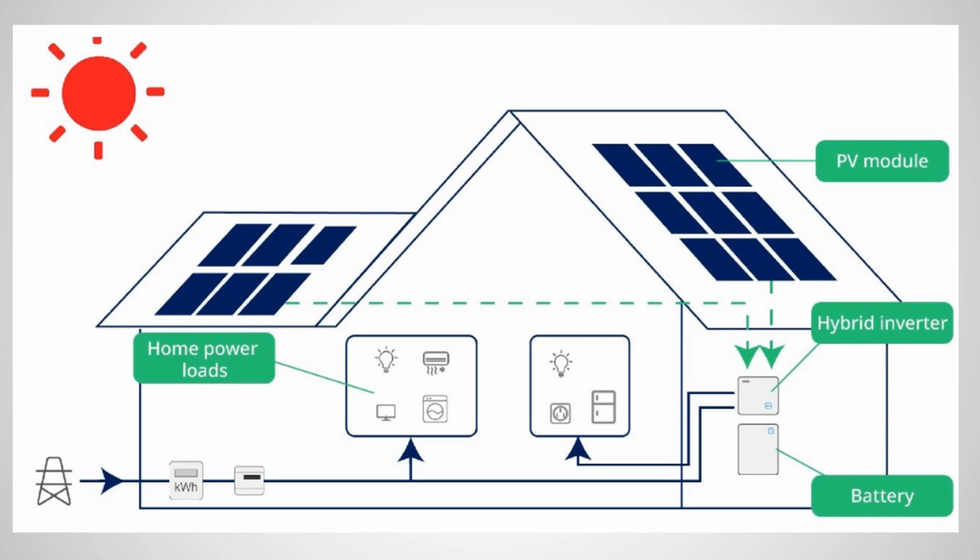So it's a nice picture here. We have a hybrid inverter in the house, and we have the grid supply supplying power to the house this way. The inverter is also supplying some other loads at the same time. It is also possible to divide the load into two sections: one section supplied by the grid, another supplied by the inverter, and at the same time it's charging the batteries. So all functions are possible with a hybrid inverter.